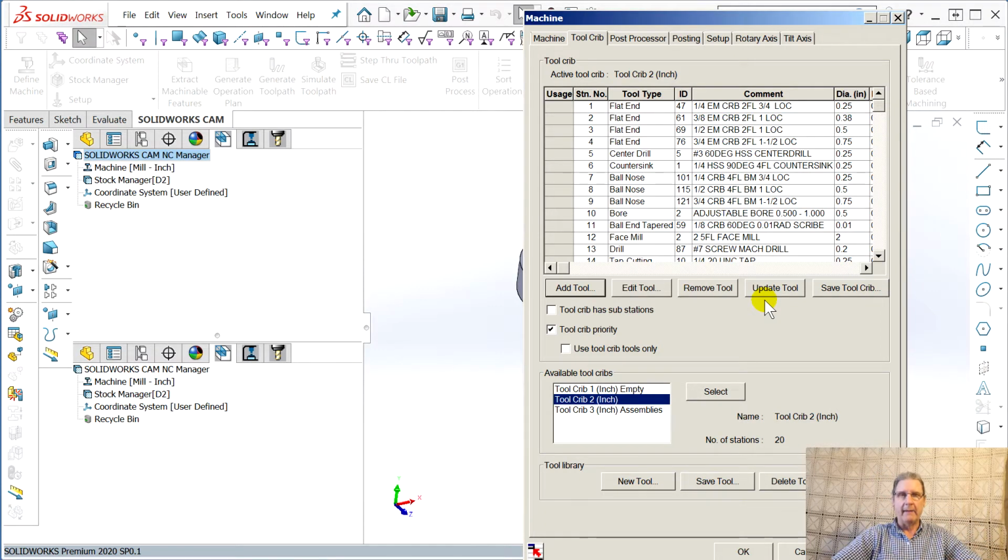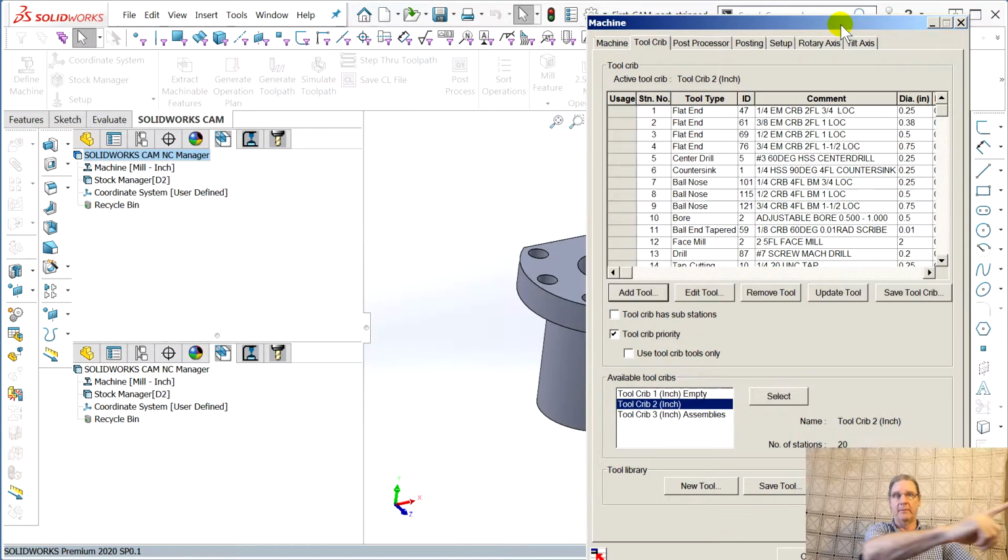You rename that, and then SolidWorks opens all the dialogues in the default position, because that key is where it remembers where you closed this window. It doesn't help. That's why it took me so long to figure out. If you close this window, even if you reset the dialog box to the default, it'll still open up in Never Never Land. So you're going to see me dragging them on and off to the monitor, where if it closes in that monitor, it reappears in that monitor the next time. Kludge, sorry, got to deal with it.